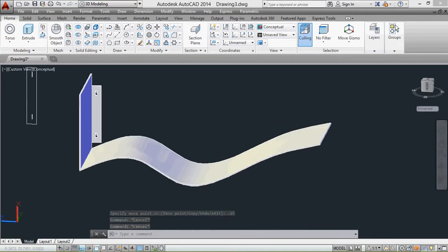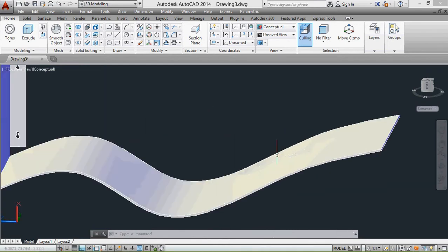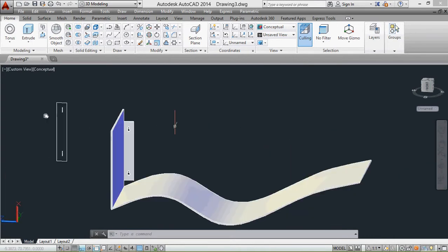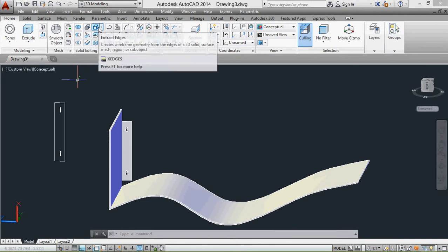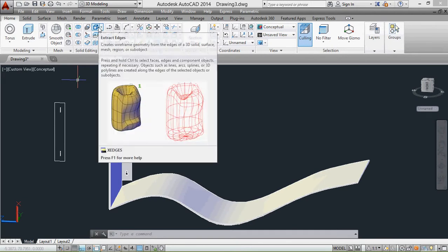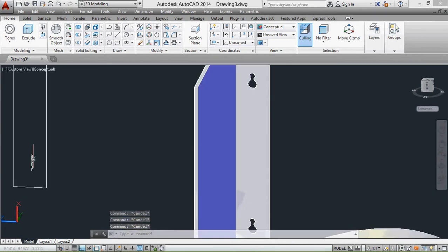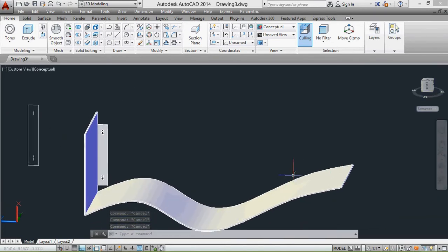Now if we want, we can use that same piece for position here, but that's going to be too hard because the shape here is not perfectly square. So what we're going to have to do instead is use the convert, it's called extract edges. Other programs it's called convert entities. So I'm not going to need this sketch anymore. I'm going to delete, actually I might need the holes. I'll leave the holes. I'm going to need that for the holes for this part here.